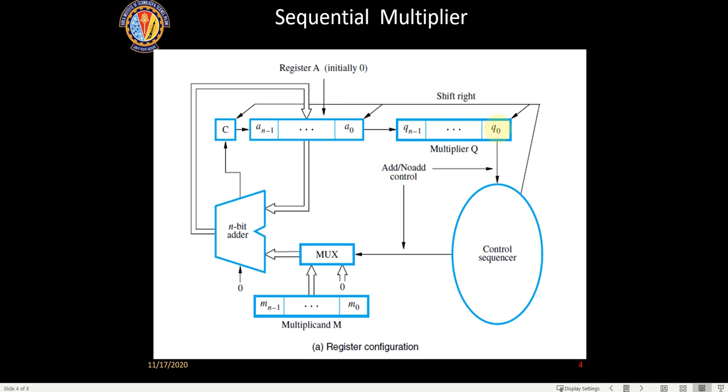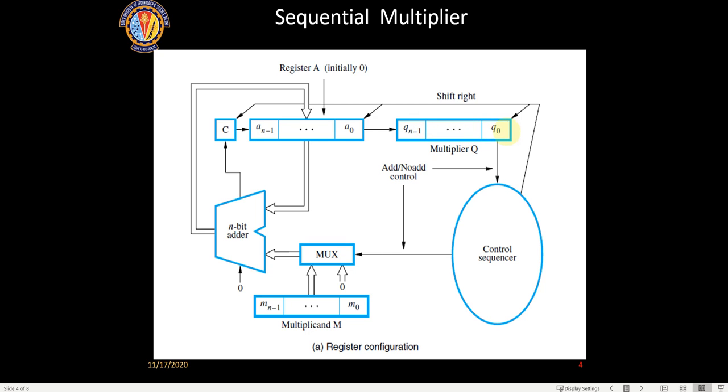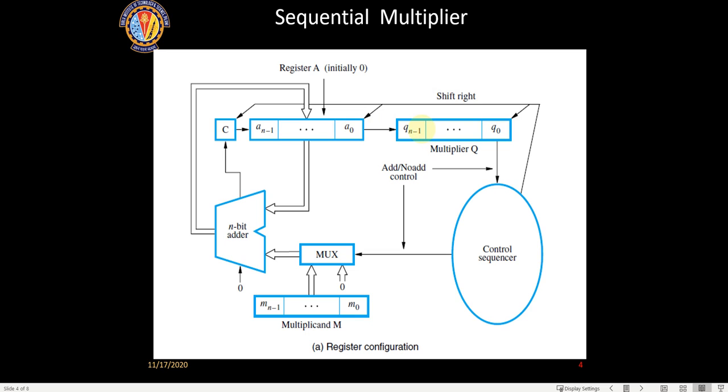Okay, in the negative edge of the clock, this particular data is going to be shifted right. From here the last bit will be thrown out, so this one is going to be thrown out, and here it will become 100, and from here the last bit which was 0 here would come here, right? Is it okay till here to all of you?